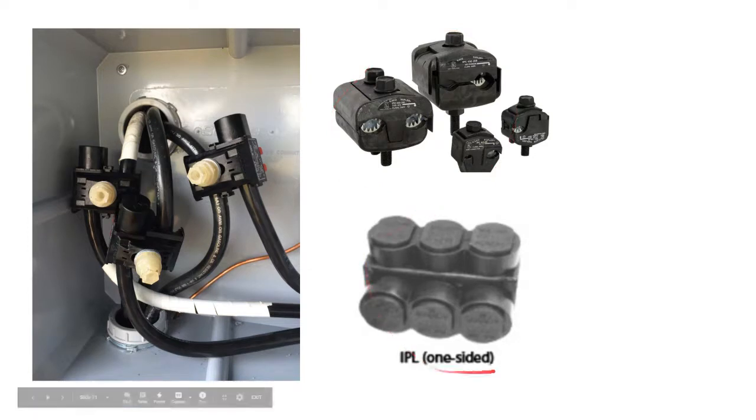Standard tap connectors require cutting the conductor, stripping back the insulation jacket, bending the conductor wire, and other small tasks which require time and hand strength. The piercing insulated tap connectors simply crank down onto the conductor. But if the building can sit without power for a couple hours, most electricians will prefer to use the regular tap connectors where possible. Regular tap connectors are less costly and easier to reconfigure at a later date than their piercing insulated tap connector counterparts.